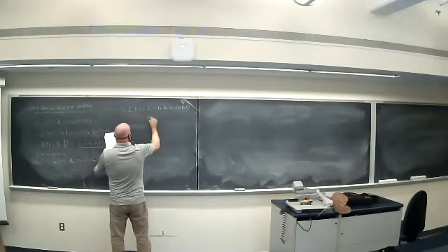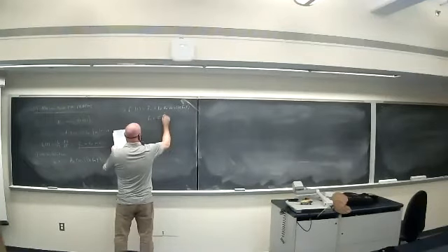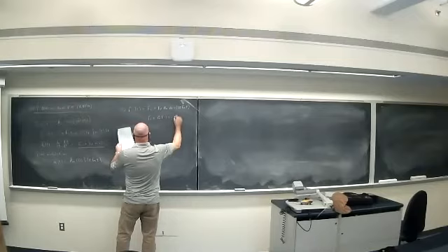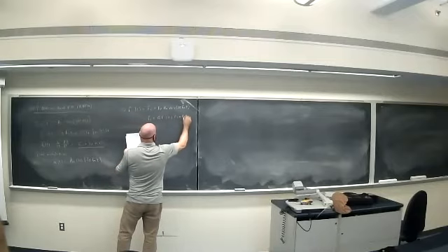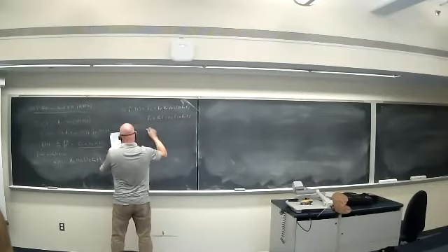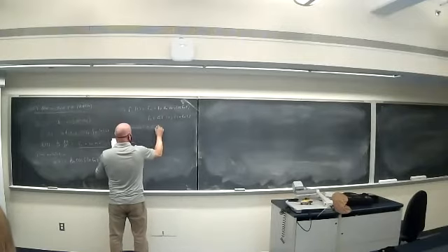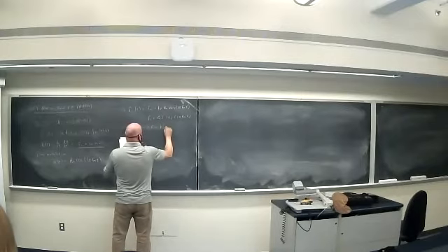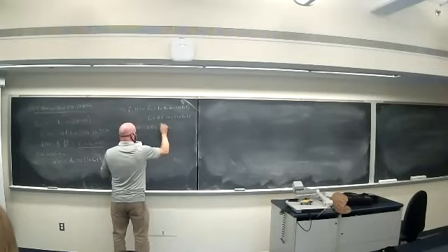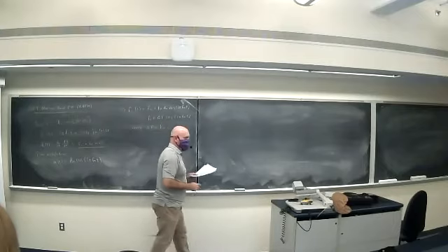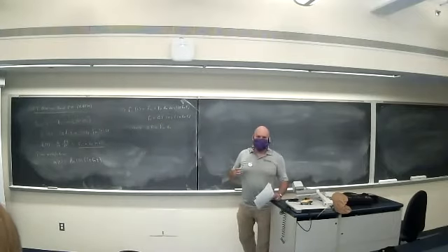Or FC plus delta F cosine of 2 pi FM t, where delta F is KF times whatever our FM modulation constant is, that KF times the amplitude of our tone.